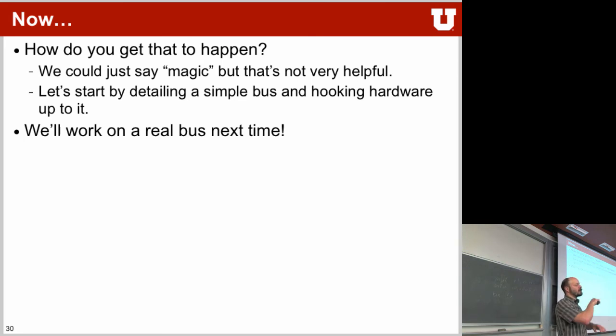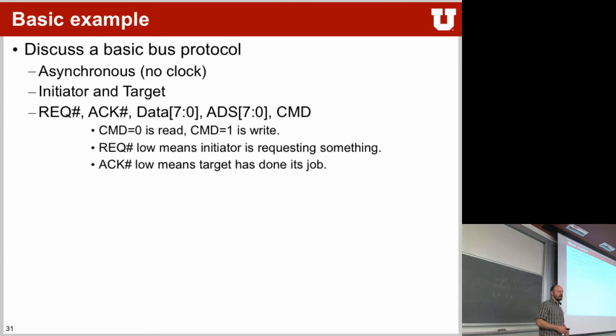That's how your data from the microcontroller, or from your core, goes out onto the bus to the peripherals. They will decode it and then do a certain action on it. In this class we will do a very basic, simple bus. And next week, we will start looking at the actual buses on our ARM Cortex-M3s, which are a lot more complicated than this little bus that we are discussing right now.